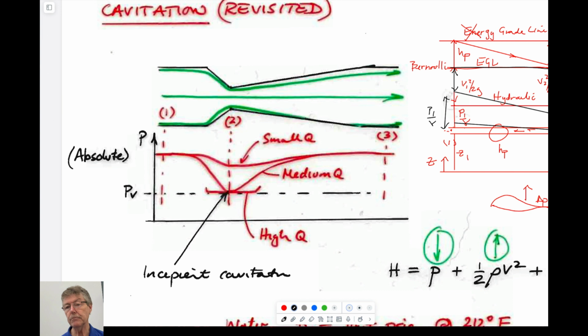And it's actually no different from what we talked about in terms of this, right? If it accelerates through here, and it is accelerating in space, it's going at this velocity, and it's going at this velocity plus some here, so as it goes downstream, it's accelerating. So not only is the change in velocity changing with time, if you're anchored to this particle and going downstream, then the velocity is increasing as you go downstream. So the velocity increases with time. I won't draw that, right? At this time here, it's 1 meter a second. At this location here, it's 2 meters a second.